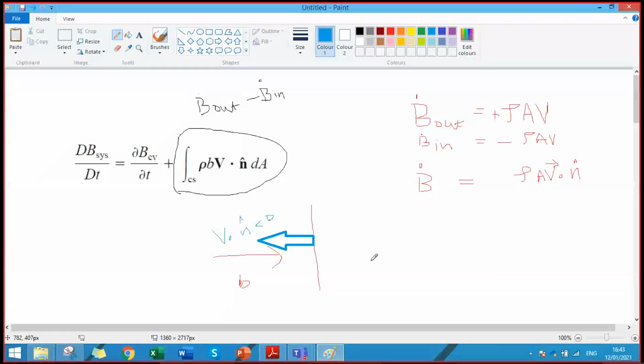Negative sign. Then when this same flow crosses over to the other side, now what happened? Now you will see the area normal of the other side of the surface, right? In that case, they are parallel, and V dot n would be positive, greater than 0. So it would be an outflow. Clear?